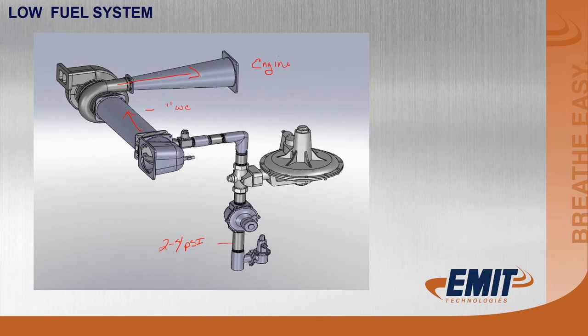Now what happens is, as you start to load that engine and the boost pressure comes up, the restriction comes across this. Now we're going to set this fuel over air. Again, here's our water manometer, and we're going to tie this to the fuel, and we're going to tie this to the air side. And with the restrictions of the air cleaner and just the velocity of the air going through there, we may start out at a light load at 5 inches of water column. But when we get under a heavy load, we need less fuel. The regulator actually backs off.